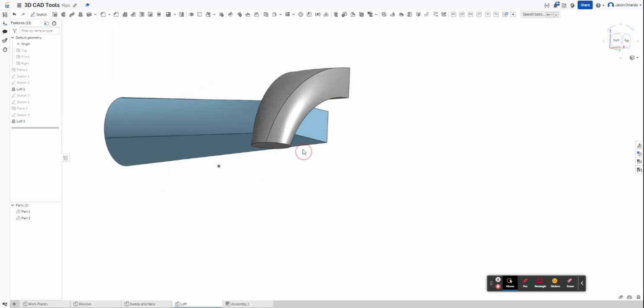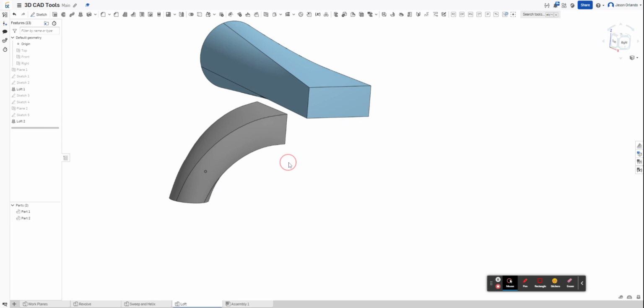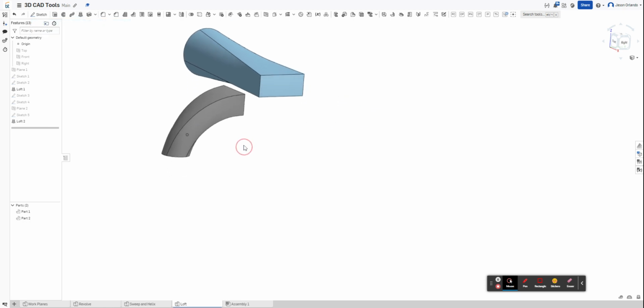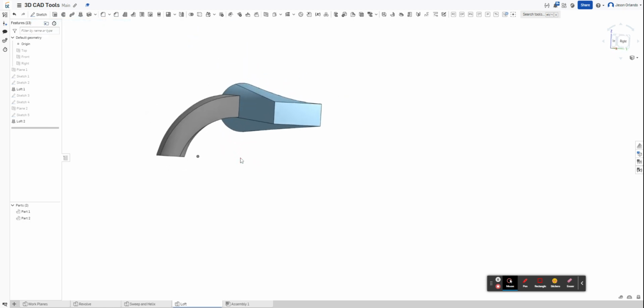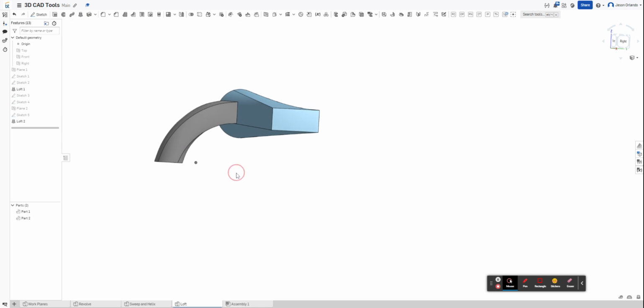Okay, so there you go. That's the basic of a loft, transitioning between two different faces, two different sketch regions. They can be, but don't have to be, parallel. Here it says create, add to, subtract from, or intersect parts or surfaces by placing a smooth face between ordered profiles. So you can also use more than two profiles to transition further, from 1 to 2 onto a third.